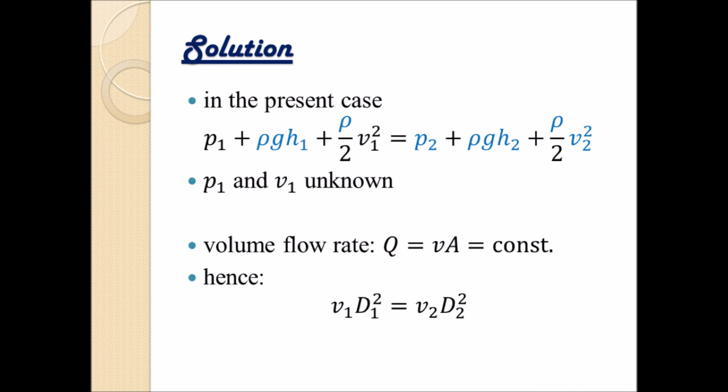And if we do the same as in the first equation on this slide and we color all our given variables, then we see that the diameters are both given and we know the velocity V2, so we can, strictly speaking, directly calculate the velocity V1 of the fluid in the basement. In addition, we can take this equation now and put it into the top line.